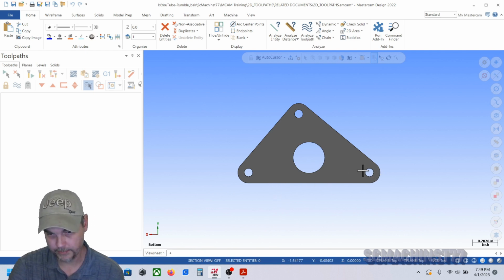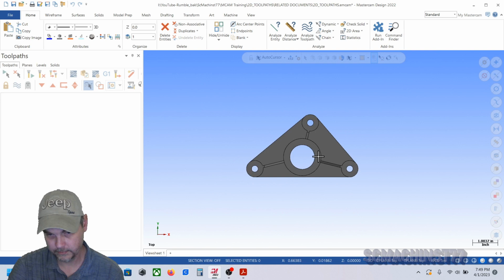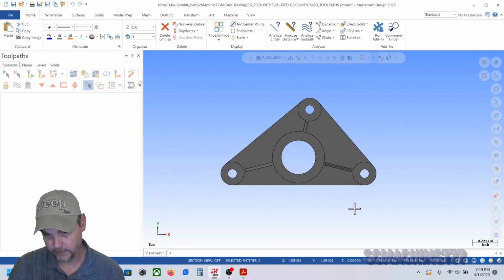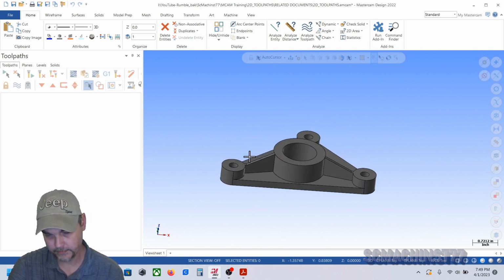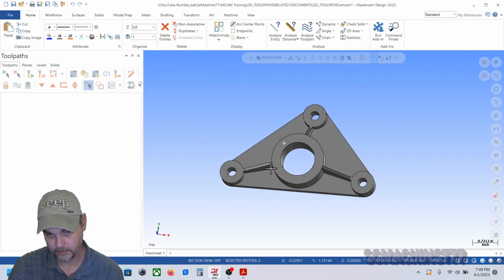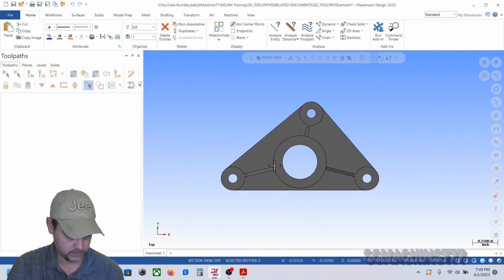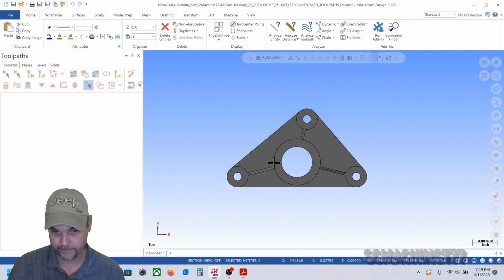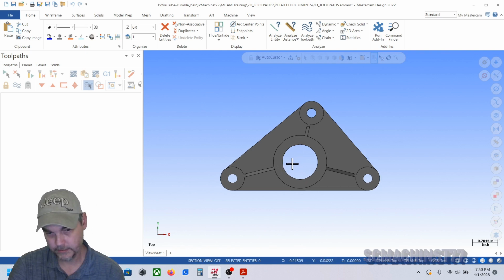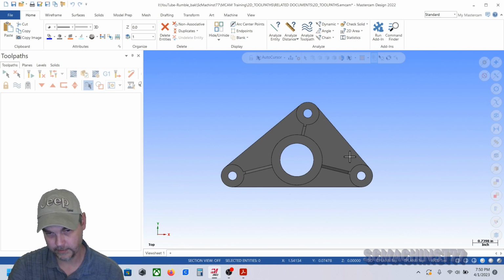Then on the next op, what we'll do is we're going to go ahead and rough all this stuff out, rough all the holes out, mill the different steps, do all the roughing that we can. We'll probably release the part from the vise and then reclamp it so that if it has any stress in it, it'll move, and then finish the part on this face, finish all the holes, and